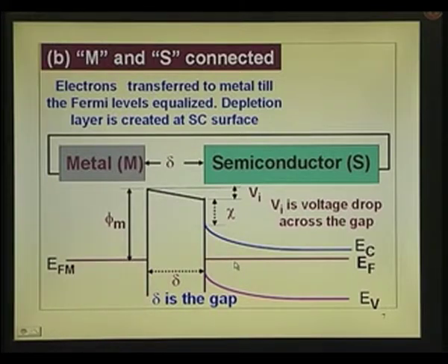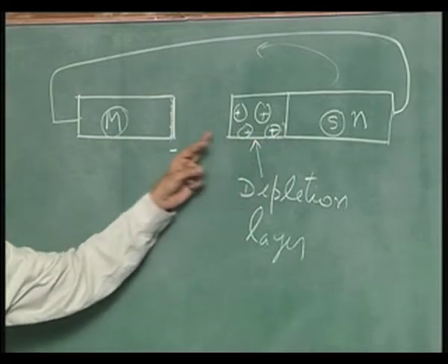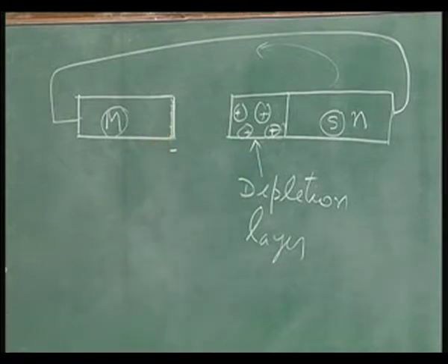The whole thing is because now the energy band diagram has tilted with this side positive and that side negative. Wherever the band bending is there is potential change. So, there is potential change from this end to that end. This is plus and this is minus. So, the charges which originate over this region, they terminate here.